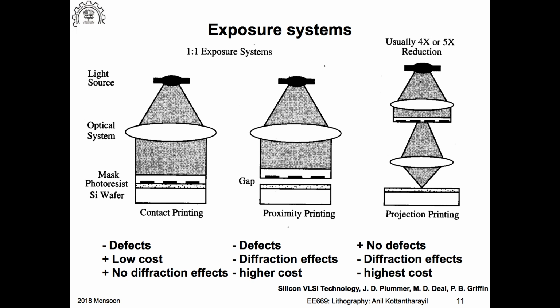Once you do lithography, you may have some photoresist residues on the mask, which have come off your wafer during this process. So this can lead to defects on the mask as well as on your substrate. So I need to clean this mask, ideally after every exposure. So it tends to be very simple, but then there are some disadvantages.